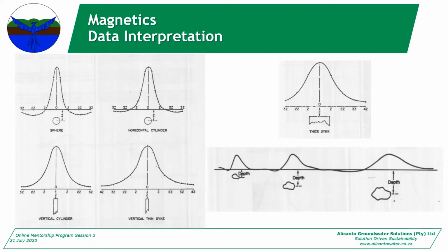It is nice to do the drilling supervision as well, just to see if you're right. But you don't have to, because often a client will say, let's site the boreholes and see if there's any potential. Then they'll have to go get some more funds, or get some investment, and then they'll come back and drill at a later stage. Because your geophysics survey will cost you, let's say, 40 to 50,000 for a MAG or an EM survey, but your drilling will cost you between 60 and 150,000 per borehole.